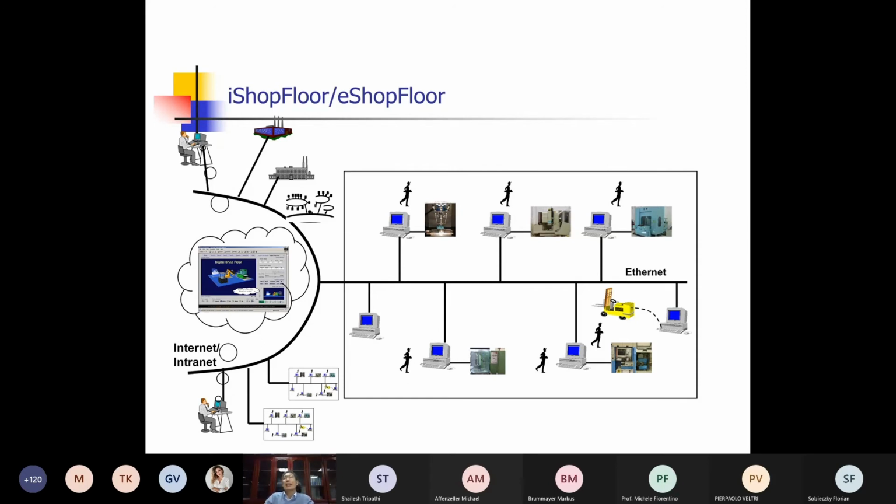In an agent-based manufacturing environment, the scheduling is done through negotiation. At the shop level, there is a request for jobs to different machines. Different machines can submit their bids, based on their availability and their capability, and then one manager agent, a coordinator, will, based on the bids received, assign jobs to different machines. So it's a negotiation approach among different machines.